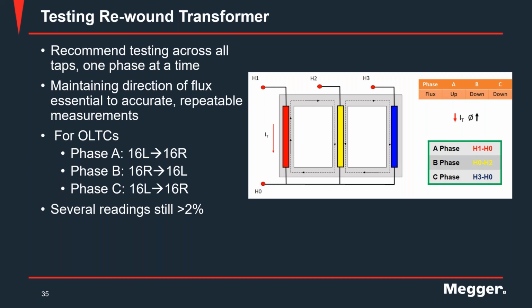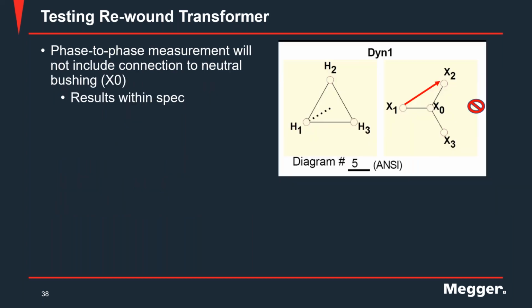if you have a three-phase source injecting currents, then you have to deal with the summation of currents and take the right value of the current, and also take into account where you are measuring the voltage drop to accurately calculate the resistance. So my point is, it is possible to do three-phase injection, but the method is more complex and sometimes not accurate for individual phase values. So again, certainly possible, but sometimes problematic.